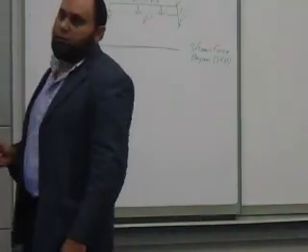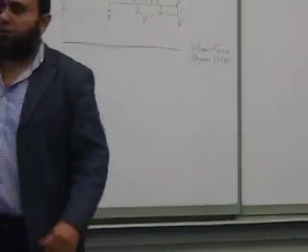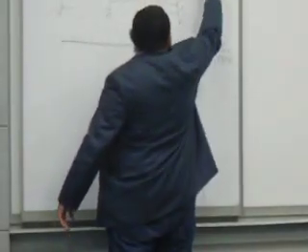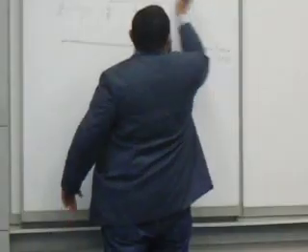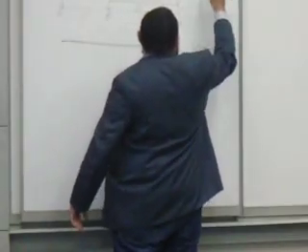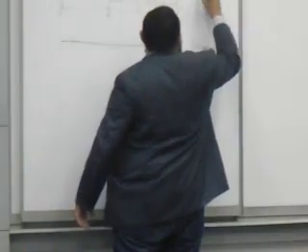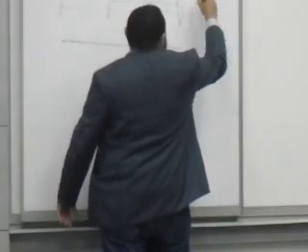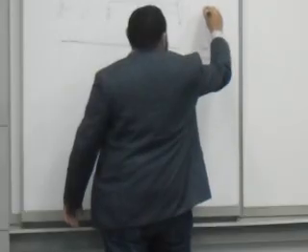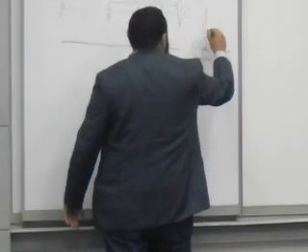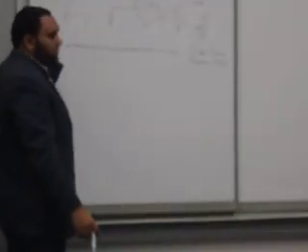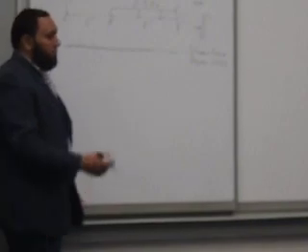I forgot to mention that the sign convention for the shear force, when we are taking a cut and looking left, is that what's up is positive, but if you're looking down, what's up is negative. So here, this is the positive case, and this is the negative case. So that's why it's always easier to take a cut and look left. You'll see now.